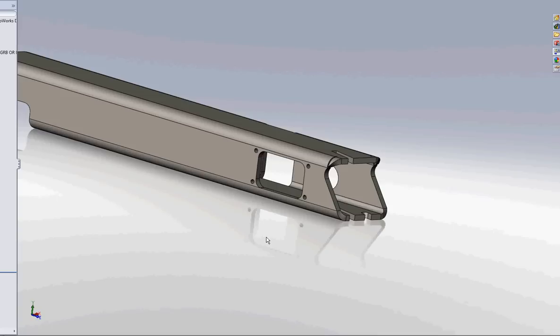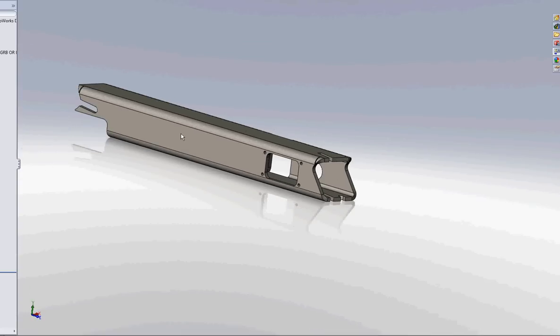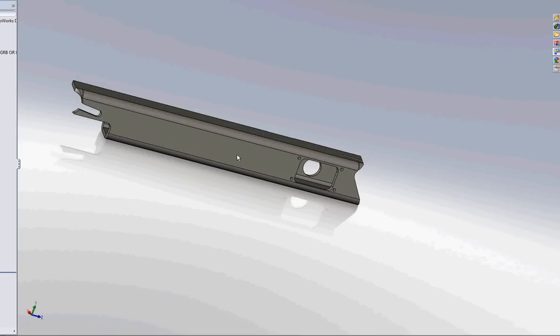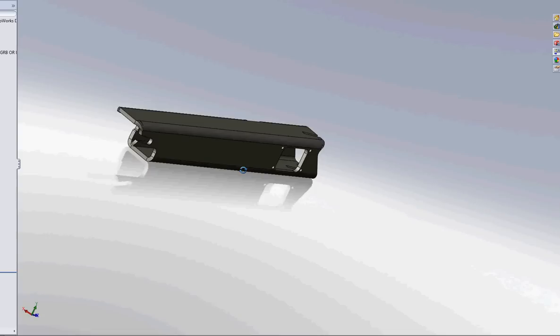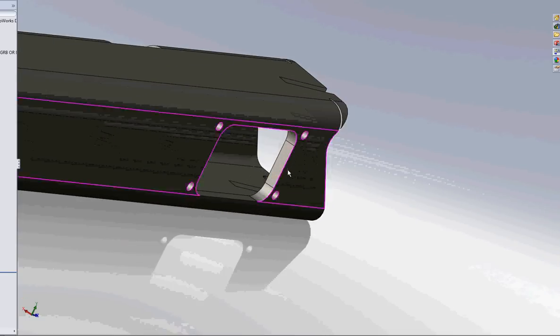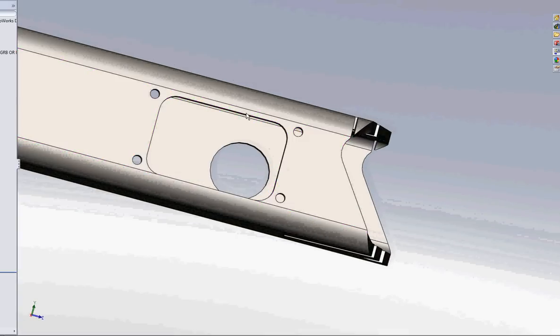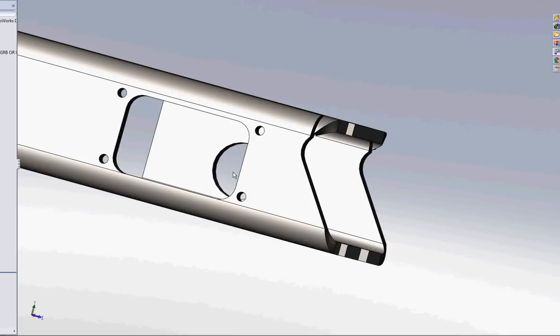So I will usually say, once I've built a prototype and proven this part out, as long as I've got good procedures and good lockdowns and my rev control, I'll trust my laser program. In which case, I'll give the quality department a few checks, IDs and ODs, just to check laser offset is really what it comes down to.